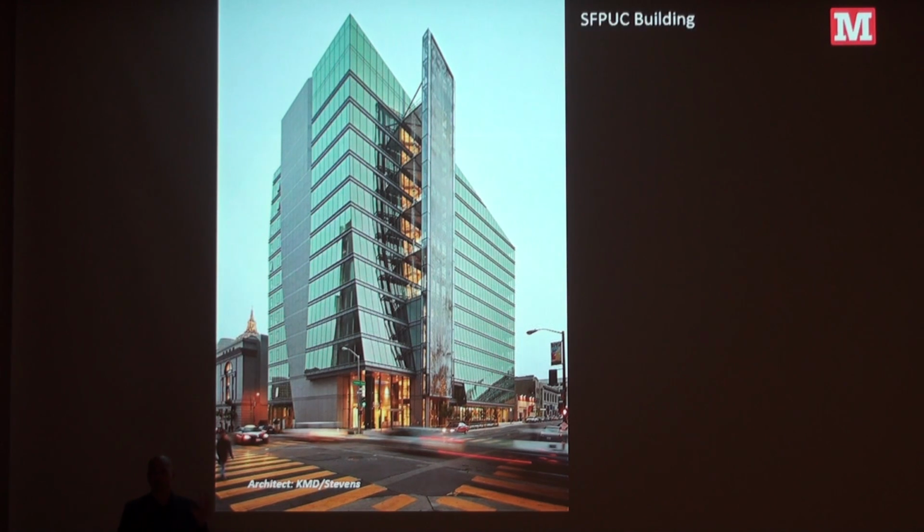After a really brutal value engineering cycle, they found they were still $10 million short. There's a $130 million budget, and they had just gone through this nasty value engineering cycle. Now the builder, Webcore, knew some of the work I've done in reinforced concrete, and what I came up with, sort of borrowing from the bridge world, was the idea that you take concrete walls and put vertical post-tensioning down the middle of them. When the earthquake happens, I'll demonstrate, the wall flexes, but think of this as a giant rubber band down the middle, and it springs it back.